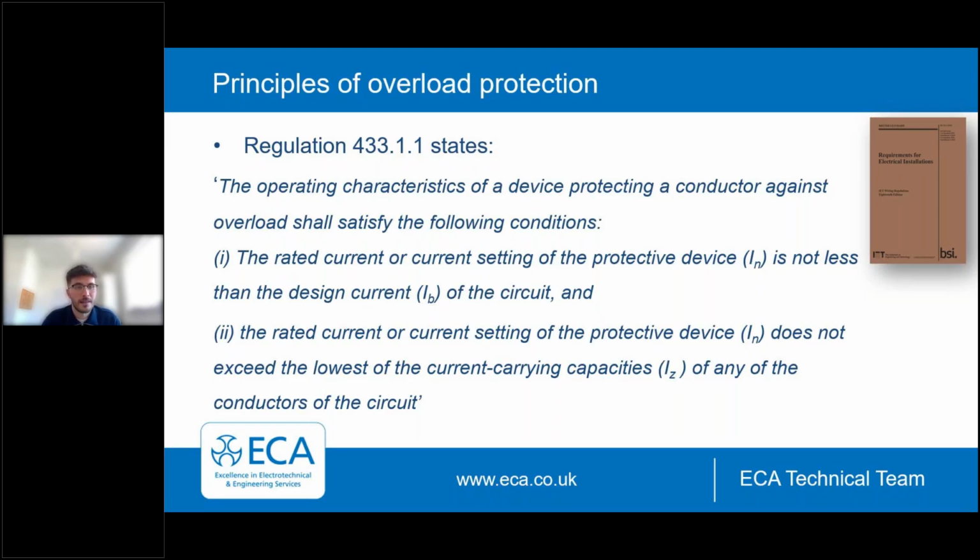So it states that the operating characteristics of a device protecting a conductor against overload shall satisfy the following conditions. Number 1, the rated current or current setting of the protective device, In, is not less than the design current, Ib, of the circuit, and indent 2, the rated current or current setting of the protective device does not exceed the lowest of the current-carrying capacities, Iz, of any of the conductors for the circuit.